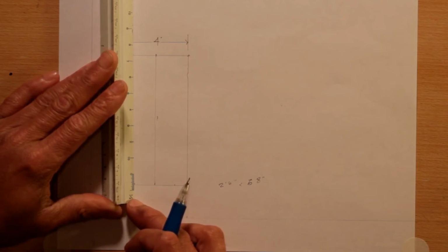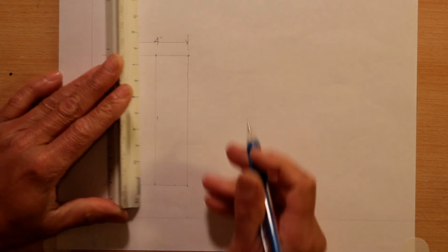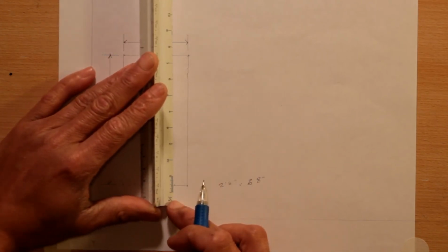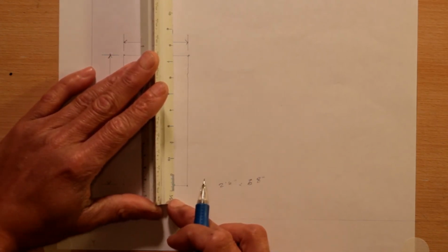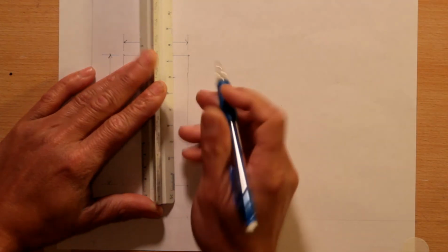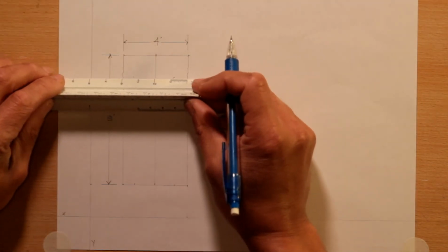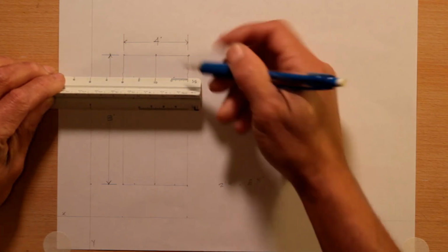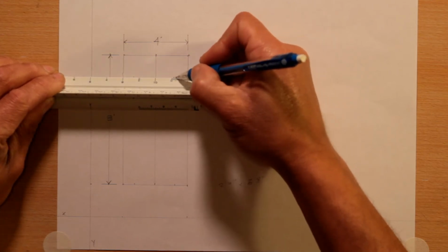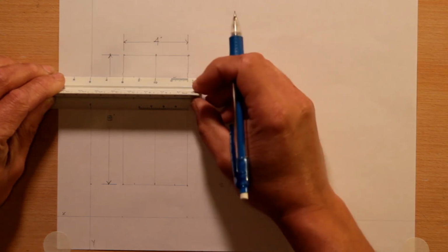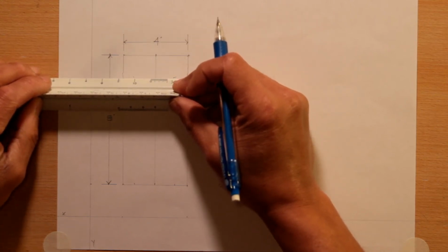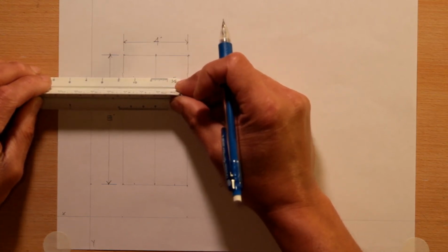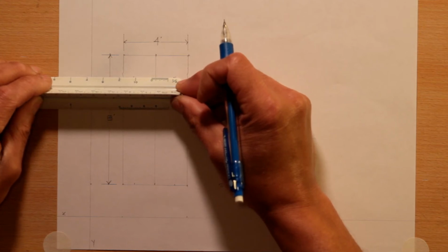Using your ruler horizontally connecting the 2 6 foot 8 tick marks, place your ruler at 1 foot on the center line. Now place a tick mark to the right at exactly 1 foot 3. Sliding your ruler to the left, still touching the two 6'8" tick marks, place the ruler at 3 inches on the center line and give yourself a tick mark to the left at 1 foot.